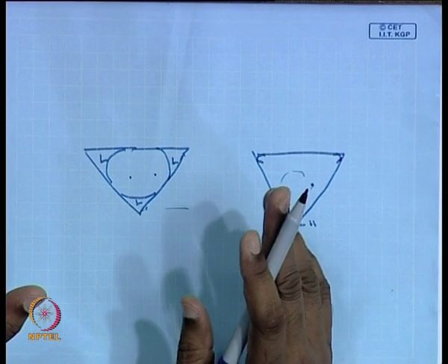Secondly, since we have the temperature drastically different between the hot side and the cold side, the surface tension will also change. The surface tension of the liquid at 50 degrees, and over a distance of 1 centimeter, the temperature is 100 degrees. So, the large change in temperature will cause substantial changes in surface tension, and the moment surface tension changes, additional flow which is known as Marangoni flow will start to take effect.